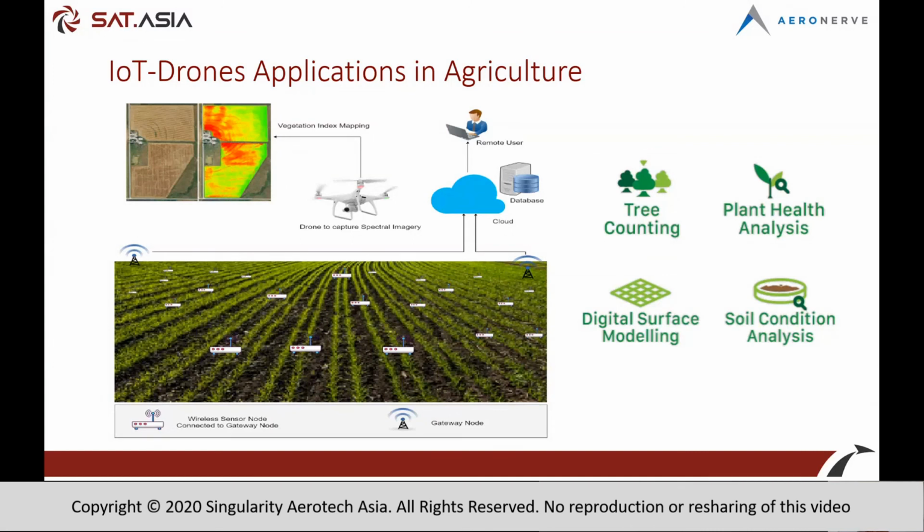The first thing, we will go on the ground. We will test first whether it's a sensor problem or whether it's an actual thing. So we have probably portable devices, something like that. So when you do that, then you will be able to know whether or not the soil is actually having the change of condition as the sensor is saying. Okay, and then we record that data.